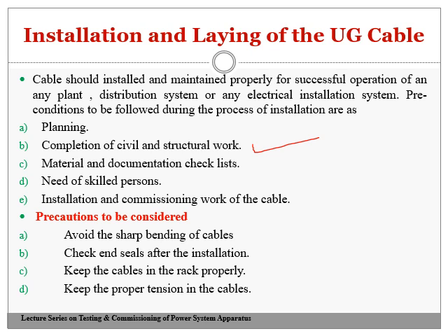Some tolerance will be given for some part of the cable. Sometimes we are supposed to bend a particular cable of very large thickness. The only thing is the bending should not be at a right angle or sharp. If it becomes too sharp, at 90 degrees in a larger capacity cable, because of the mechanical stresses at a particular joint, there is a chance that the conductors may break when a certain amount of voltage is applied and current flows. That's why the precautionary measure is to avoid sharp bending of the cables.